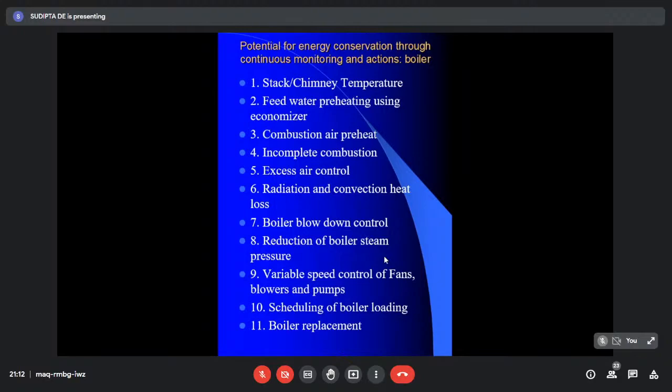Okay. Here again, I'm just stopping here because boiler blowdown has several control principles. We can make continuous blowdown so that some amount of water will always go out in a very controlled small amount. It can be intermittent blowdown, and in the blowdown process also, continuous monitoring of water is required. Actually, impurity presence is identified because when the boiler is operating, you cannot identify how many impurities are already there inside. So this is done by an electrical conductivity process. If the impurities increase, then the ions increase in the boiler. So conductivity increases with the appearance of ions.